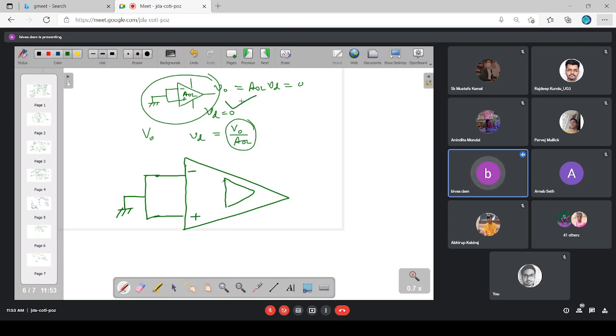But this is not the case here. Here, this is one practical operational amplifier. Though the input terminals are shorted and grounded to 0, the output is coming as a certain non-zero value. So that's one practical operational amplifier. Inside it, we are assuming, I am forcing on this term assuming, that internal to the practical operational amplifier, there is one ideal operational amplifier